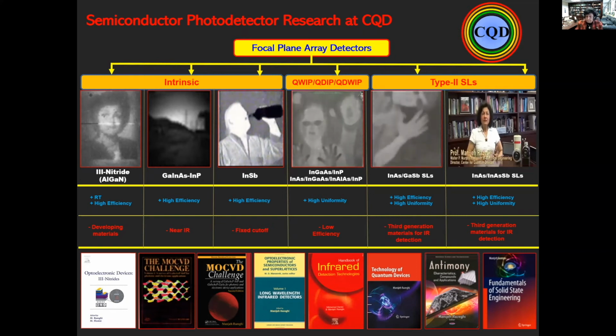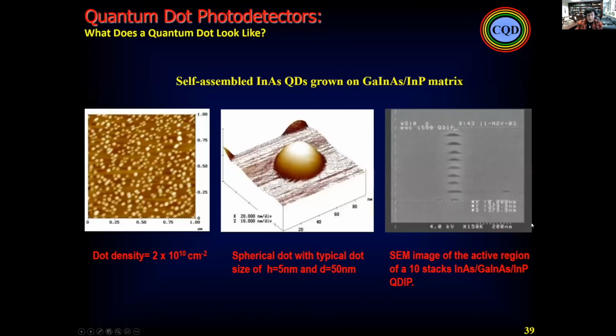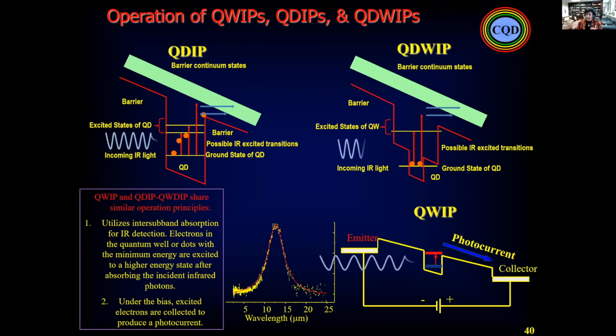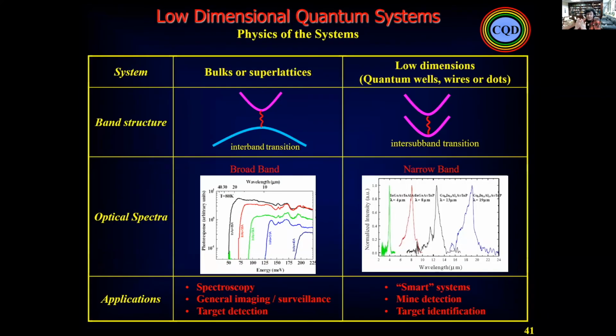For that, I would like to come first to the quantum dots. Exactly as I mentioned, that is the future. Quantum dots, quantum wire. But what do we have at this present time? We have the quantum well infrared photodetector. But if we go to the quantum dots and quantum wire that we demonstrated, we can have much better performance, much higher quantum efficiency, and at the same time much better independence of the temperature, coming to a higher operating temperature. But unfortunately, that is narrowband.